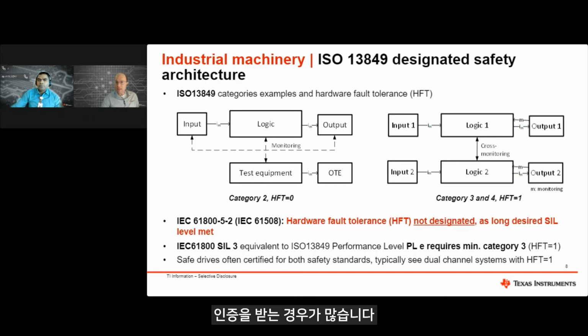The diagnostic in that case is run on a SIL 1 rated MCU, and we also have an STO feedback to the programmable logic controller. Where to get information on this design? This design is supported with a TÜV report, a safety manual, and a qualitative system FMEA, and these documents are available on TI.com in the corresponding TI design folder.